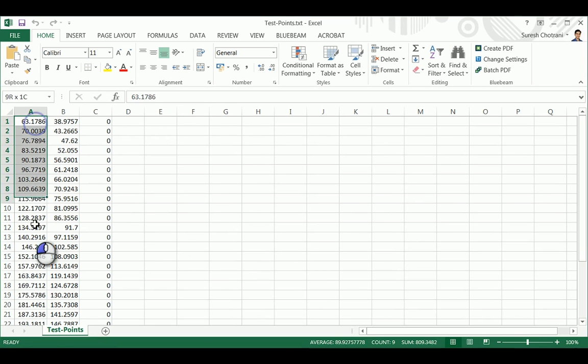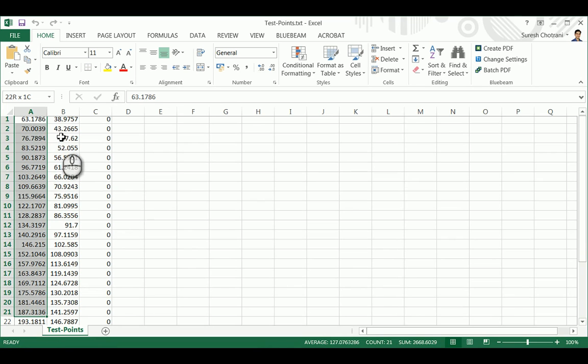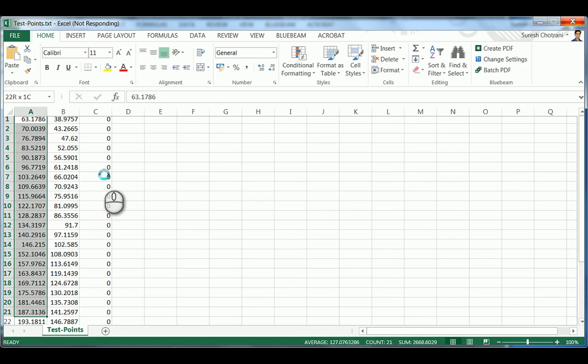So now you have X and Y coordinates from the profile, and Z coordinates will be shown as 0. This Z coordinate, as I already discussed, you will be getting from the profile, and from the profile you will be getting the center of track, and from the center of track you will have to calculate the center of tunnel. You will have to do that manually, at the current chainage the elevation will be so and so.